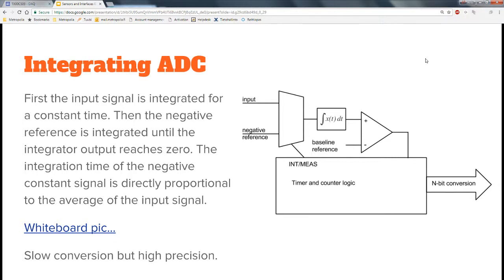Okay, what else? Even the reference voltage is not that critical as long as it doesn't change during the sampling. And on the other hand, these reference signals can be done with very, very high accuracy. And then I also told you, so basically the biggest inaccuracy here is the time.